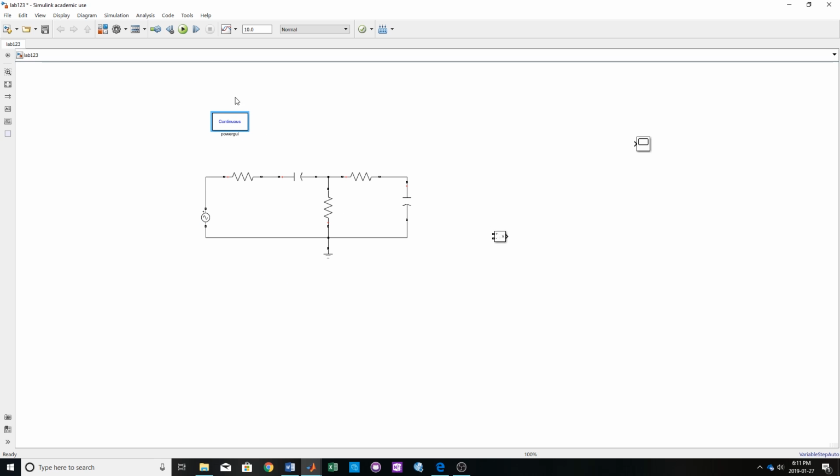All right, now you have a basic circuit. You have to keep this thing somewhere in your schematic. Okay. All right, so now you have your voltage measurement device. You're going to take this. Let's say for example you want to measure, with respect to ground, the voltage across this resistor right here. So assuming current comes like this, you're going to connect the positive lead of this measurement to the positive side of the resistor.